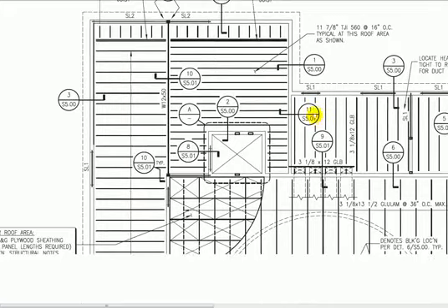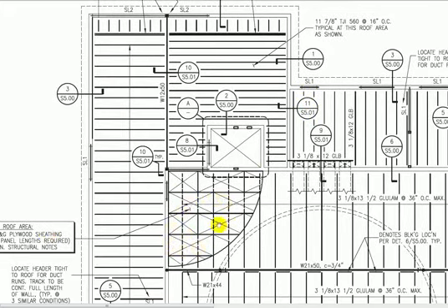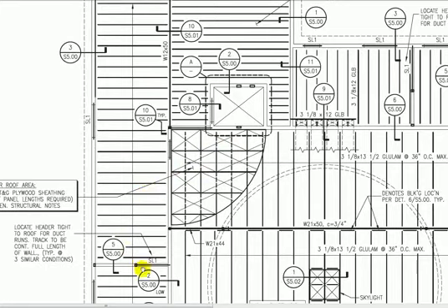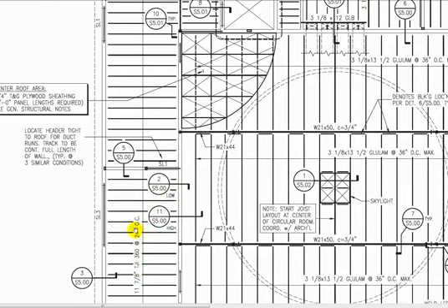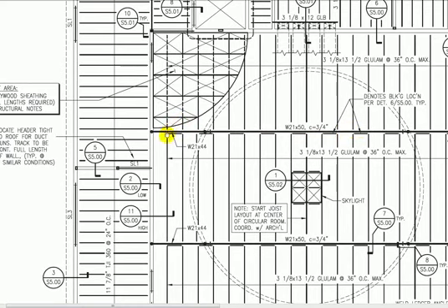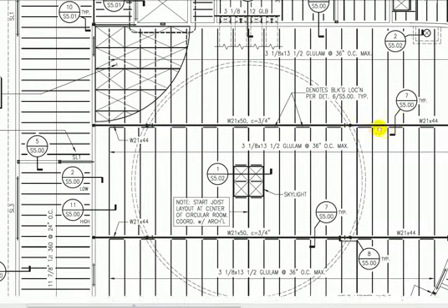If we scan around here, some roof area is plywood sheathing, and right here we have truss joists at 24-inch on center. Here we have a steel beam going across, W21 by 50. C 3/4 inch means there's a 3/4 inch camber on the beam. It looks like this little symbol here stops, so it's a 21 by 44, runs over the column, and then there's a splice and another splice there, and then we have these 3/8 inch by 13.5 inch glue laminated beams going between here.